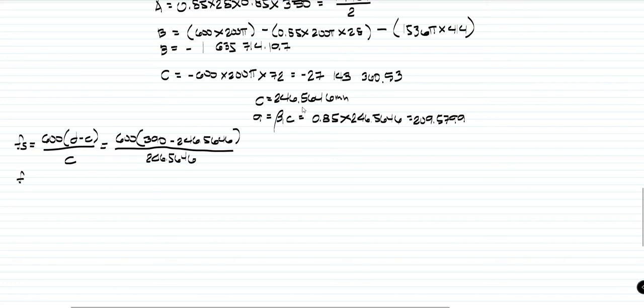So our FS now will be equivalent to 349.0413 megapascals, and this is lesser than our Fy. Therefore, our steel does not yield. So our assumption on the part of the tension is wrong. Since we assumed the tension steel yields, we have to correct that one.